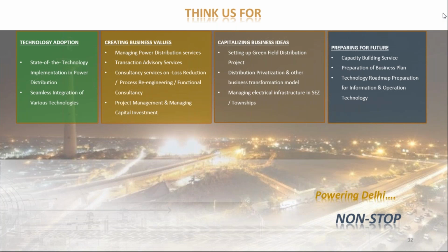So K Electric, the distribution company here in Karachi, replaced copper conductor with aluminium conductor, and they have to make sure that the conductor being replaced has the same current rating and the same electrical characteristics. But we have to consider this aspect as well, that we use a conductor which does not invite more theft of conductor. So this also has to be considered.